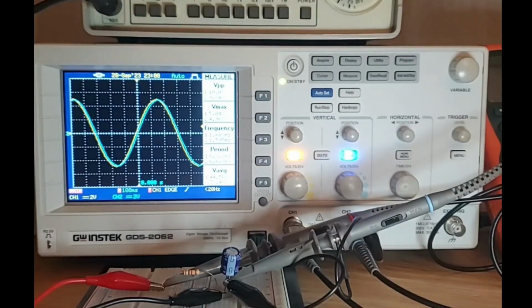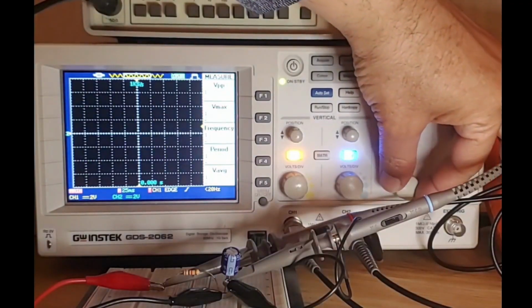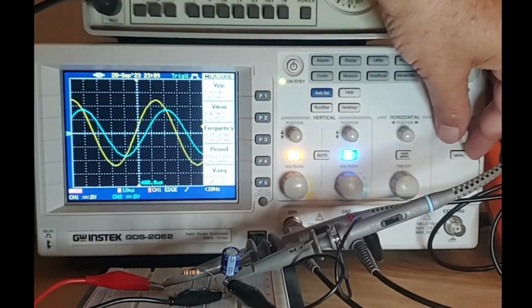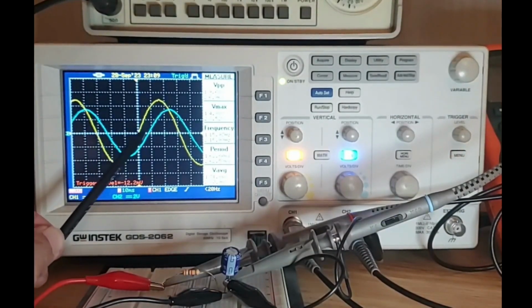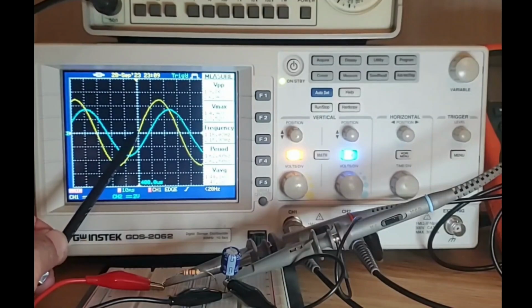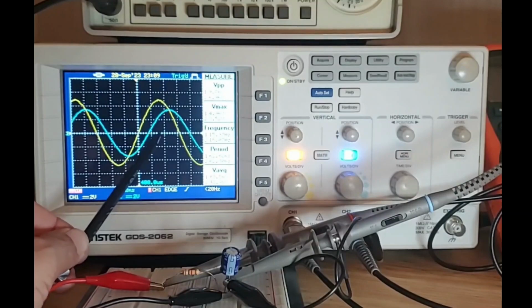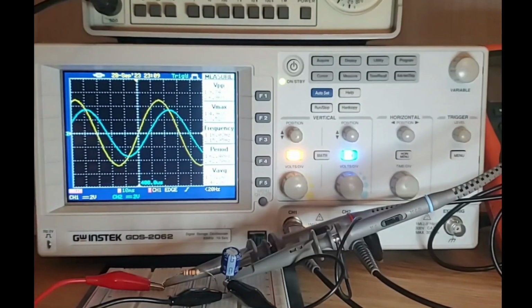Now let's do the opposite. So let's go back to the 16 hertz that we had before. This was the case when we had 16 hertz. So we had a 45-degree phase shift. As you can see, this is a 45 degrees phase shift. Also, I want to bring the trigger level to the center. So now you see that the zero crosses this point. So you see the phase from here, from 0 to the peak is 90 degrees, right? So you can now tell approximately that this much is 90 degrees. So this is therefore half of it, so that's about 45 degrees.